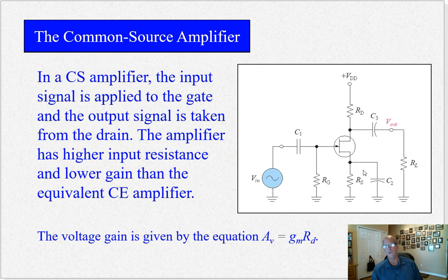So if you notice, if you put these two resistors in parallel, this becomes a lower value, right? Because two resistors in parallel give a lower resistance than any single one of them. So as you load this circuit with a heavier load, meaning a lower load resistor value, your gain goes down, and we'll see that in a minute.